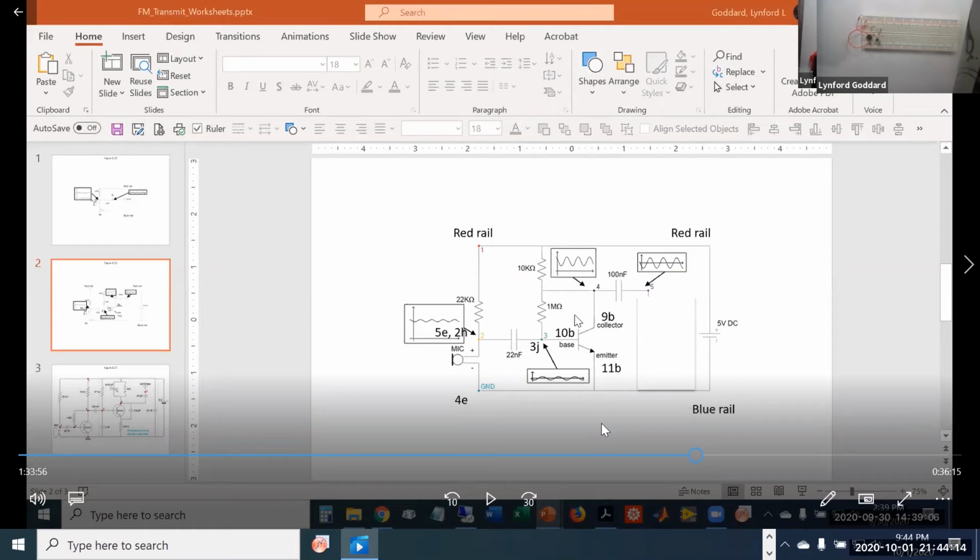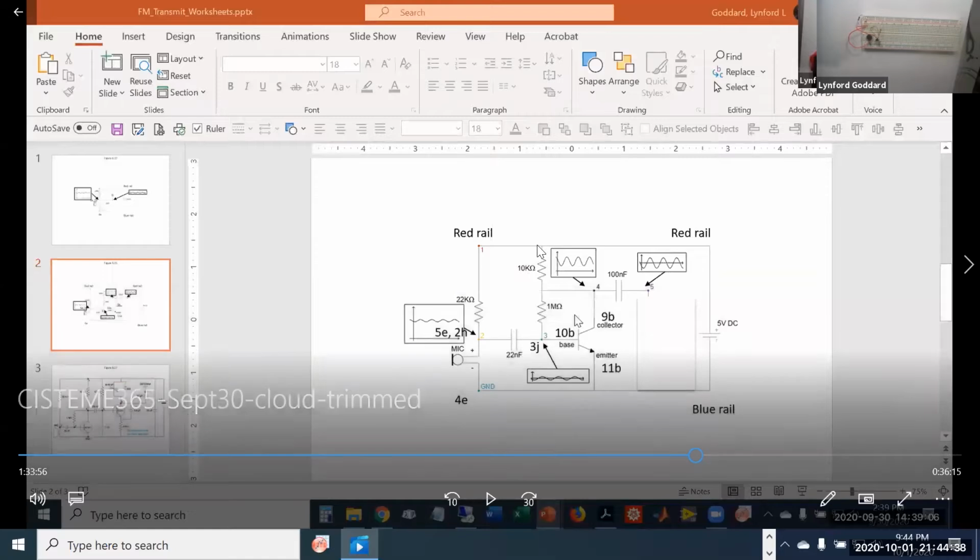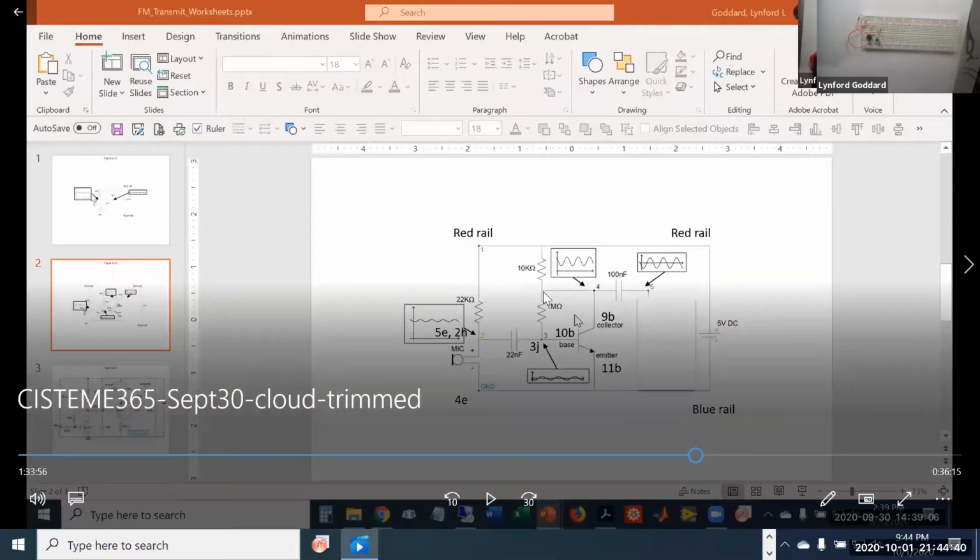Okay, so last time when we were assembling the circuit, I said something incorrect, and that's why the circuit didn't work. So I've jumped to the part of the video that shows the error, and then I'll explain it. So we were in the process of building figure 815, and we were connecting this 10 kilo ohm resistor. So in the video and the live demonstration, essentially, what I said was we needed to connect from the rail to 10, but it's actually this 10 kilo ohm needs to go from the rail to 9.